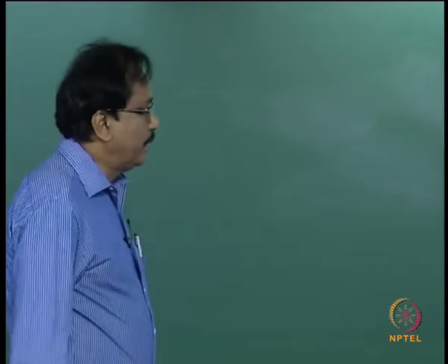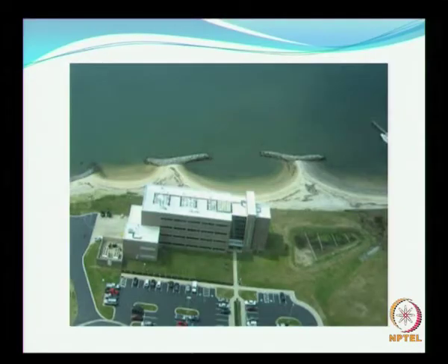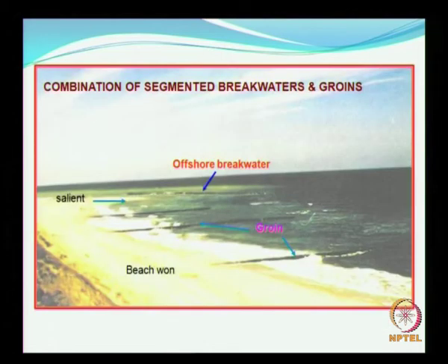So, yet another view of offshore detached breakwater, wherein this is protecting the building just adjoining the beach, adjoining the shoreline. So, this gives us a feeling for the advancement of the shoreline due to offshore detached breakwaters. Sometimes a combination of segmented breakwaters and groins are adopted. This is of course a bit expensive, but this is also being used.